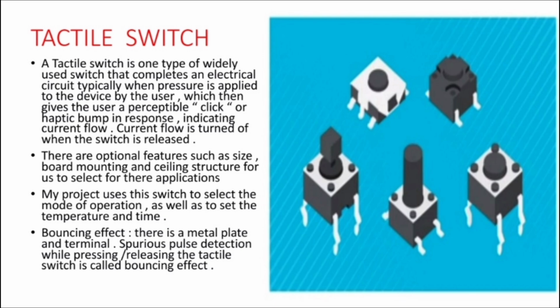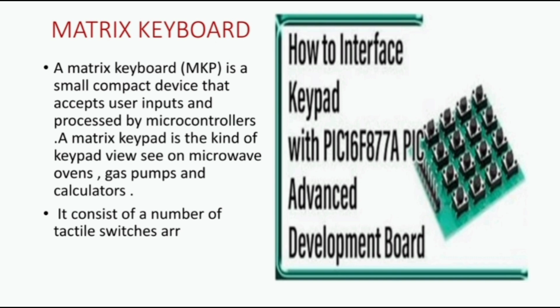Now, bouncing effect. Bouncing effect means there is a metal plate and terminal. Spurious pulse detection while pressing and releasing the tactile switch is called the bouncing effect.